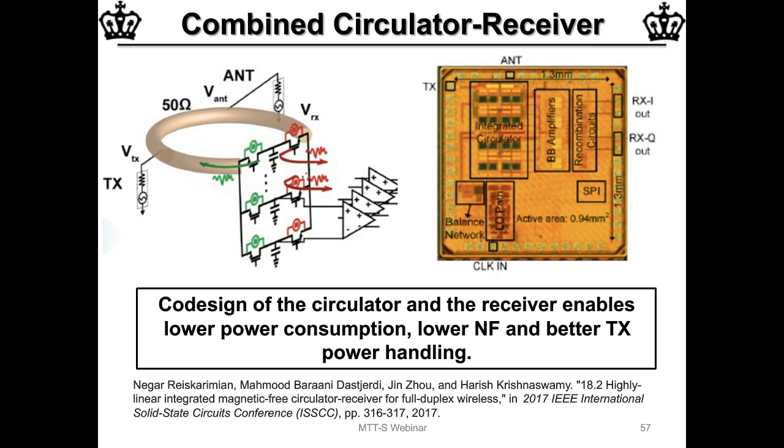And so the noise on the left-hand side, what's marked in green here, has to circulate away from the receiver because only clockwise propagation is supported. And so that noise circulates clockwise and dumps itself in the transmitter termination, while the noise of these switches here on the right-hand side, traveling clockwise, will actually appear on these capacitors and will be sensed by these baseband amplifiers. So noise also circulates just like signal does in the ring, which one would expect.